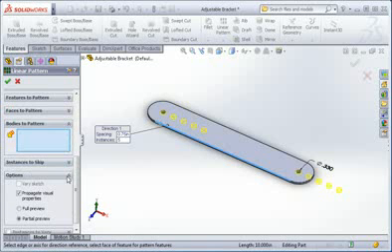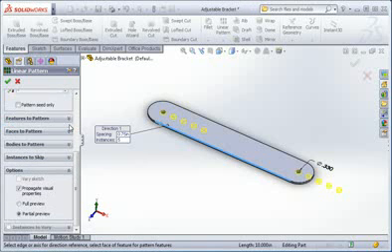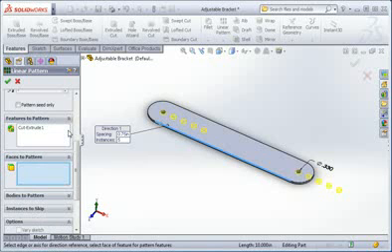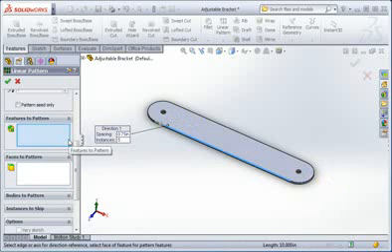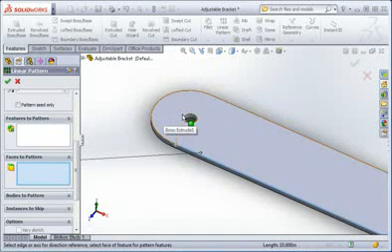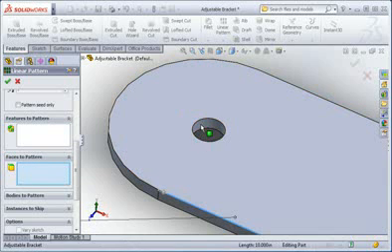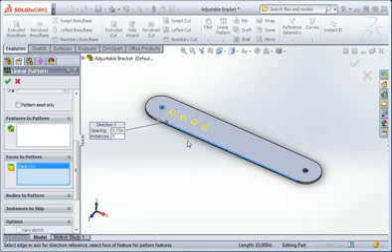You'll learn more about bodies later in the course, so we'll skip this section. And the next section is the solution to our problem. With this option, you can select a single face. Before we select the face, clear the selections in the Features to Pattern window. Now click the Face Selection window, and then zoom in and select the surface of the hole. Now the pattern is applied to one hole.